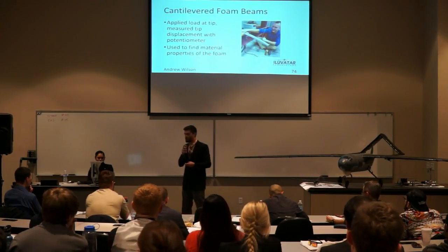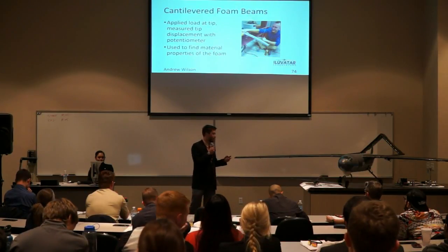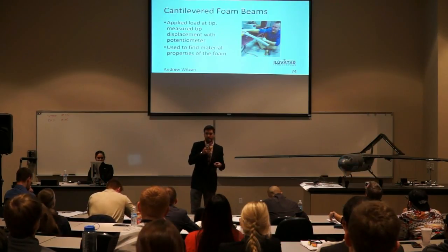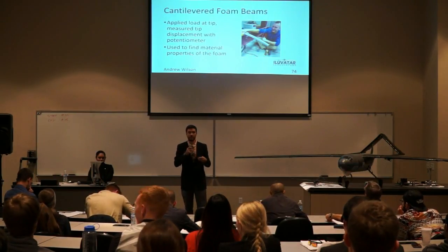For the cantilevered foam beams, we had a beam, as you can see here, fixed at one end, and a load was applied to the tip, and a linear potentiometer measured the tip deflection, which was used to find Young's modulus.